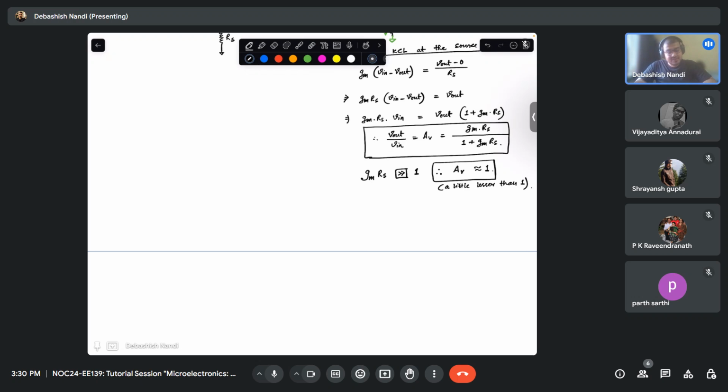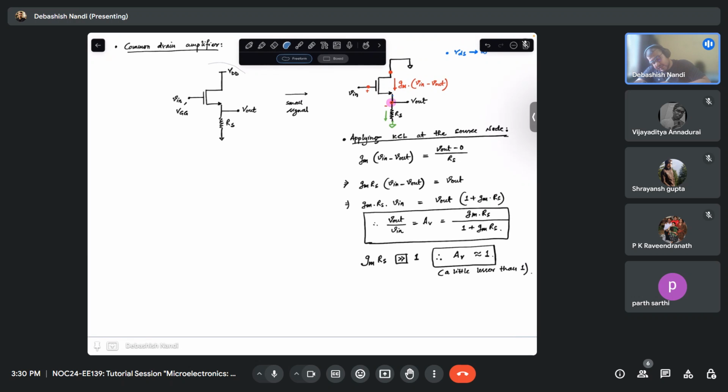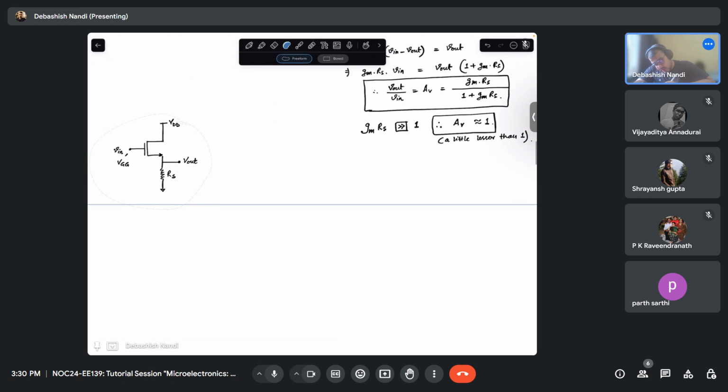So what kind of device is this? Basically, this device, if I just copy it, this device is equivalent to an amplifier with a gain of 1. So what is it called, by the way? Buffer. It is called a voltage buffer. Okay. You remember in the first session I discussed the importance of voltage buffers in circuit analysis.